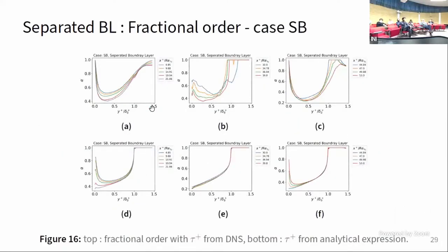It's the same idea with the DNS velocity. In the usual cases when we had a viscous sublayer, the fractional order was unity, but within the recirculation bubble, we have a stress term that is non-zero, and there exists non-locality. The construction within that recirculation bubble gives corresponding results.